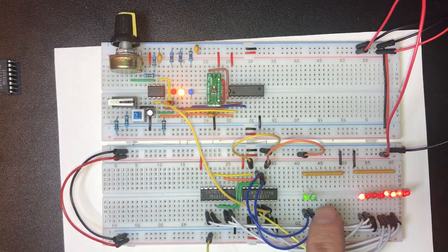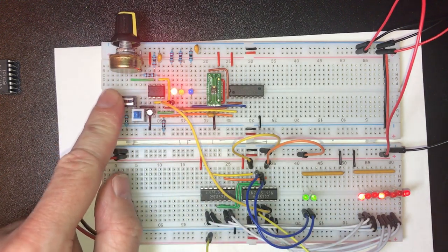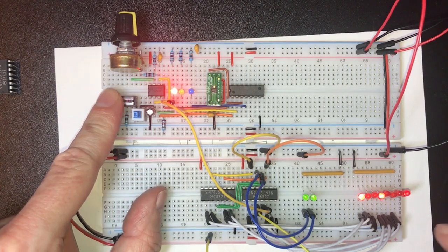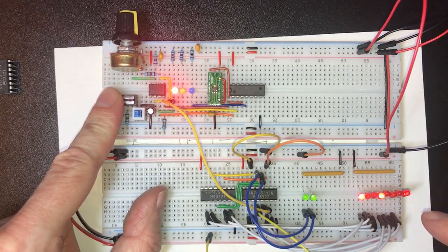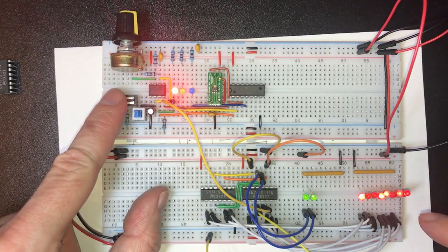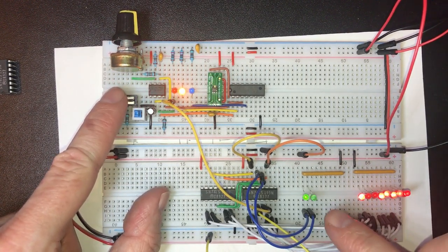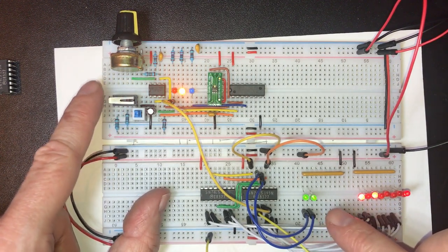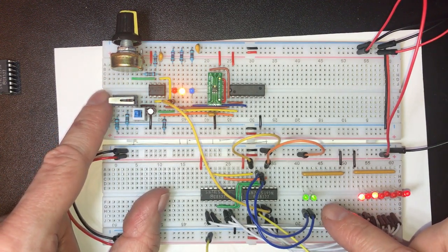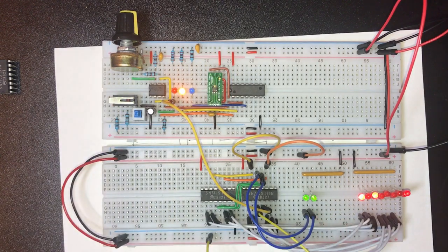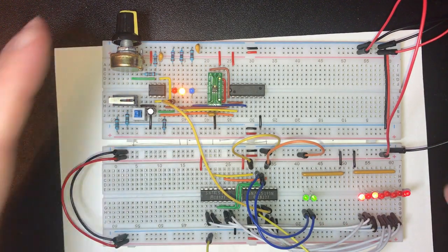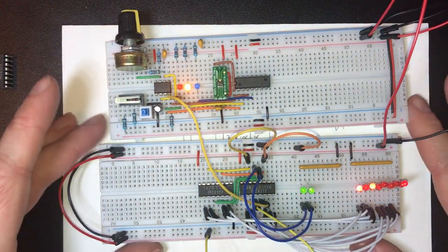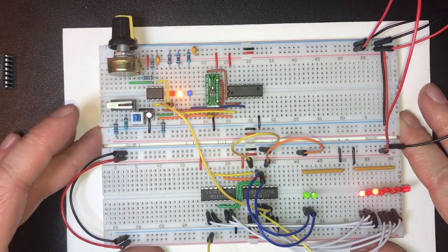So once I get to a point where the next clock is going to be carrying over, the LED goes down, and then on the rising edge, the carry happens. So effectively it's kind of like preempting the fact that it's going to have to carry, and then it carries. So we see the carry or the borrow change for half a cycle. I'm not sure why they've done it that way, but we can certainly work with that.